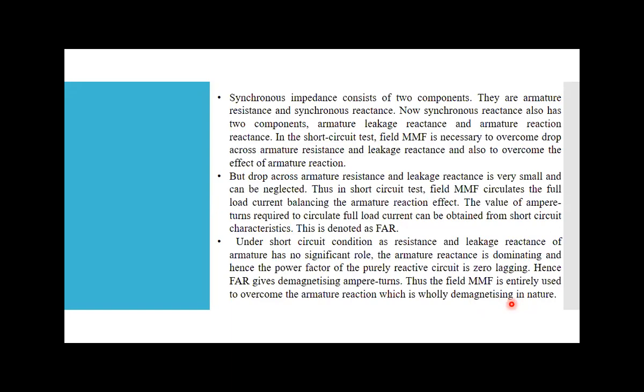My armature flux opposes the main flux, so the overall flux will be reduced. As the overall flux is reduced, it is demagnetizing. In the capacitive case, my main flux and my armature flux are both in the same direction, so the total flux increases, and it is known as the magnetizing effect.